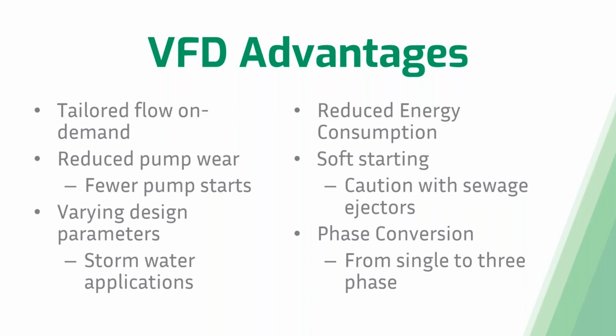Another thing is you can hit varying design parameters using a VFD. This is fantastic for stormwater applications where you may want a pump that can handle, say, a 100-year storm, but you also want to be able to drop that pump's operating flow downward towards more of a 10-year storm during normal conditions. So then that way you have one pump fulfilling two roles in that application. Another thing is VFDs help to reduce energy consumption by pumps.